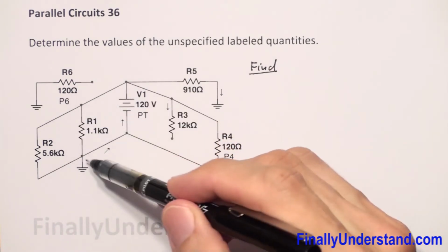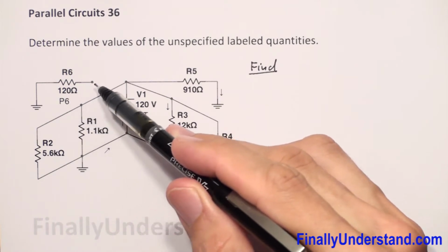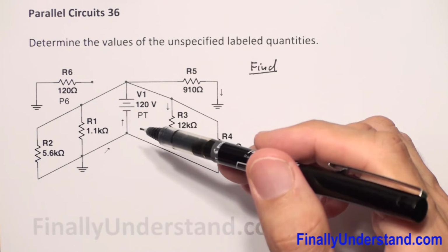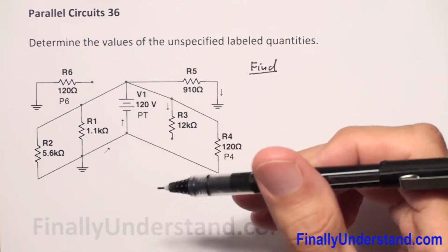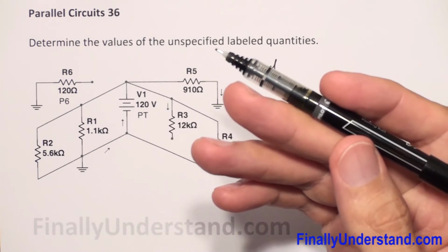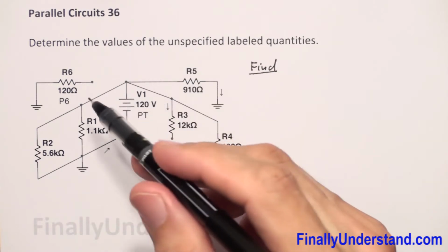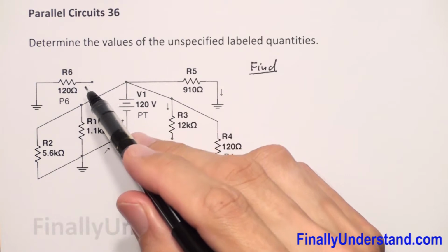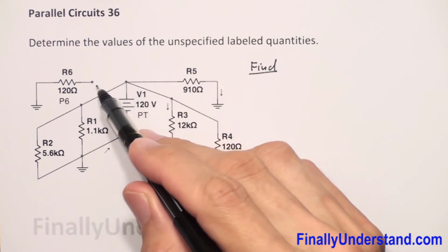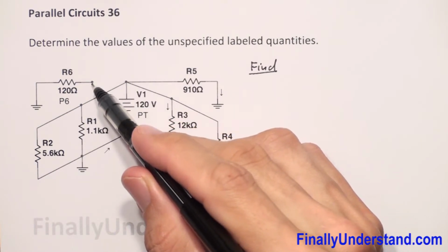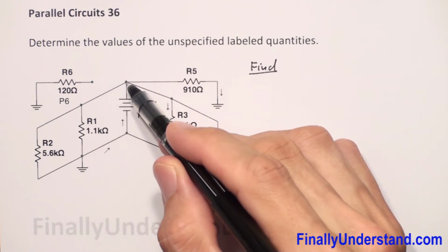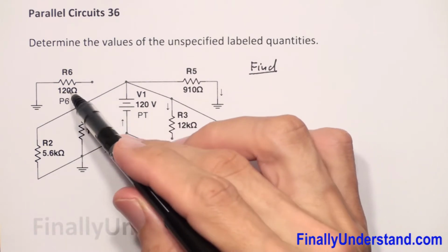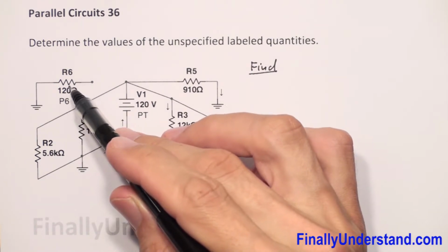It's connected only by ground, a resistor connected by only one terminal to the circuit. It simply means that that particular component is disconnected. So this resistor is disconnected from the circuit. It's like an open circuit over here. See, there is no connection from this point to this one, right? So you are connected only to ground, but it doesn't mean that current flows through this resistor.